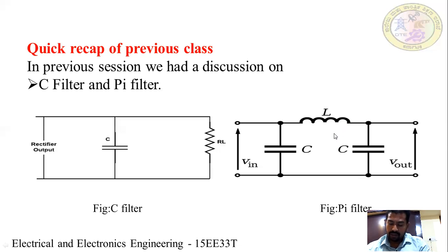And it blocks the AC component and doesn't allow it to the load. It gives only a DC component and allows it to the load. This is the other capacitor, C2, which allows the remaining AC through it and filters the AC content present in it, and it gives almost pure DC for the load.